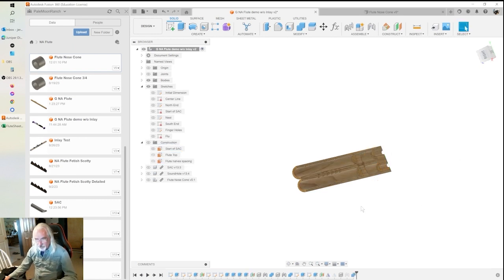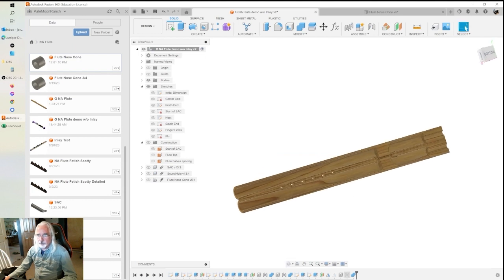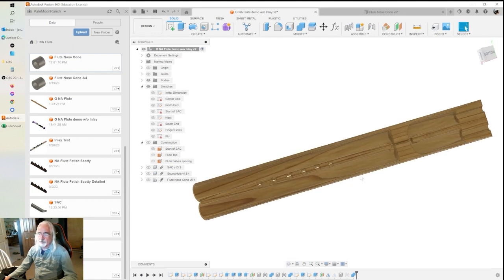Now, to cut the inside, the first thing we got to do is make some adjustments here, because when we do a morph spiral to cut these insides out, it's going to cut everything it sees, including these holes and including the flue. And we don't want it to cut those right now. I want to cut those when I'm doing the top, because I get cleaner cuts on them that way. So I need to hide these so that it doesn't try to cut them.